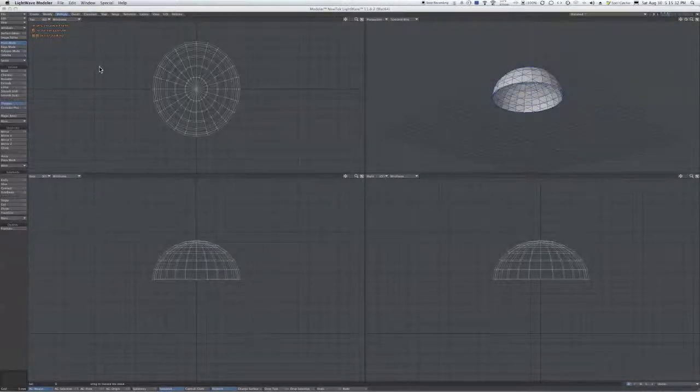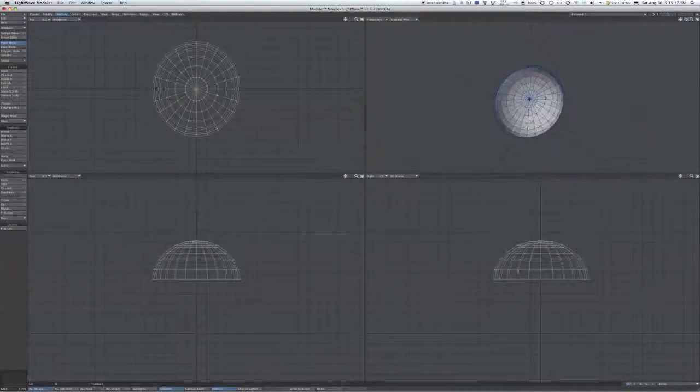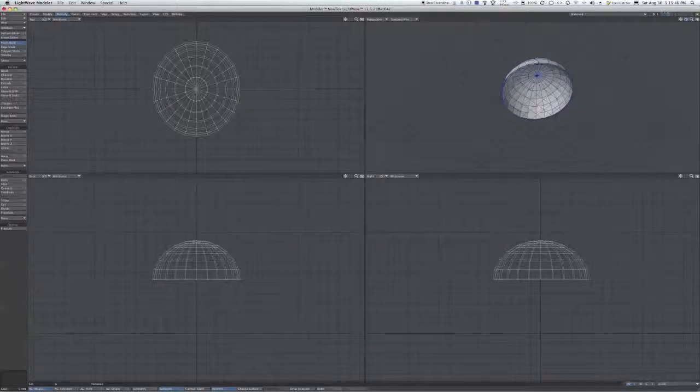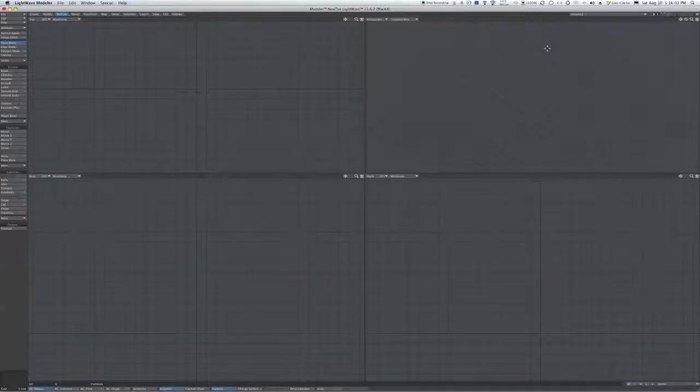I've screwed up because I don't have an edge on that. But let's assume that this were a shell like this. If your printer is calibrated well, this would actually print, because it would go up here, and up here it might have a little bit of blobs in it, but this would probably print okay. So that's some of the things to think about when you're designing for 3D print.